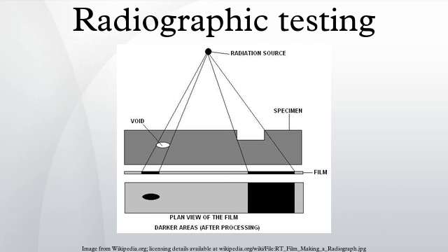Before commencing a radiographic examination, it is always advisable to examine the component with one's own eyes, to eliminate any possible external defects. If the surface of a weld is too irregular, it may be desirable to grind it to obtain a smooth finish, but this is likely to be limited to those cases in which the surface irregularities may make detecting internal defects difficult. After this visual examination, the operator will have a clear idea of the possibilities of access to the two faces of the weld, which is important both for the setting up of the equipment and for the choice of the most appropriate technique.